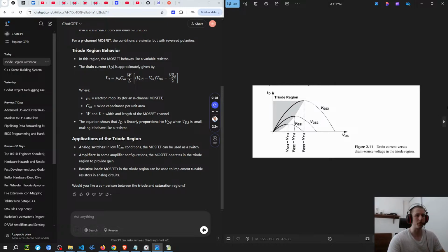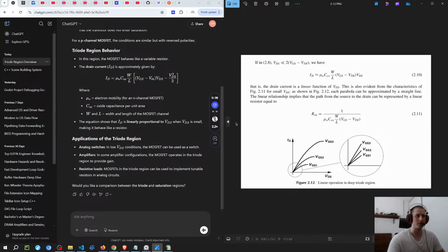And this is also important for the timing analysis, because obviously I think that the timing has to be based on the longest path of the circuitry, because you need to make sure that the rising edge of the clock synchronizes with the logic of the circuit.